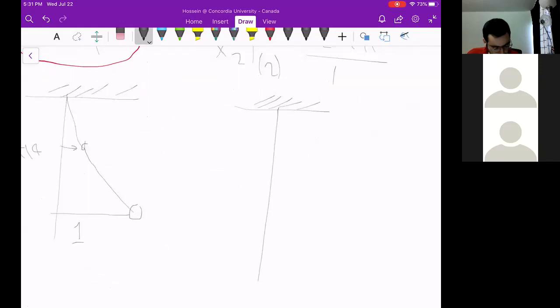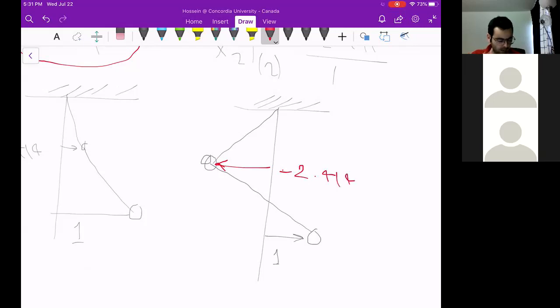But for the second mode of operation, it can be translated as if the second mass is displaced 1 millimeter, the first mass is going to be displaced in the negative direction. So the second mode shape would be like this: minus 2.4, for example, millimeter. There is a note here for the second mode shape: you could locate the node.